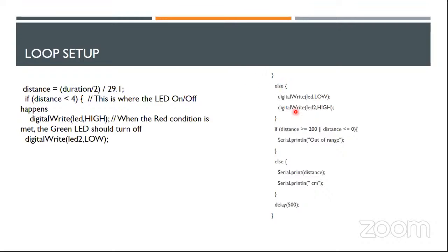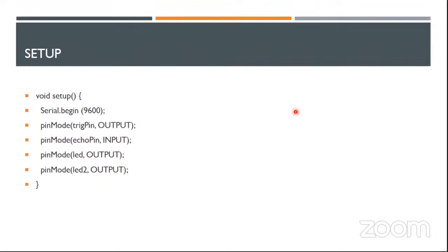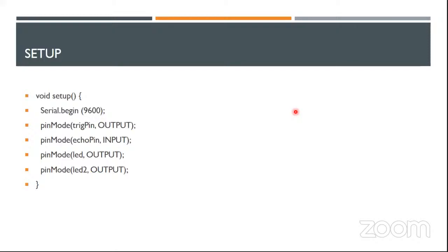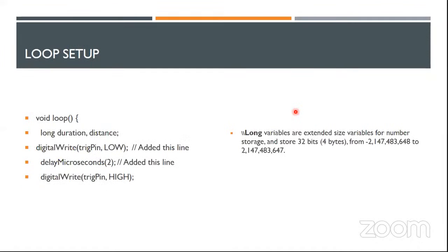So here you guys just understand, when you are going ahead with sensors, we need to make two things. One, in void setup, you need to define your input and output. Then in void loop, you need to apply the if else, loop, those kind of conditions, calculation, everything we need to define here.